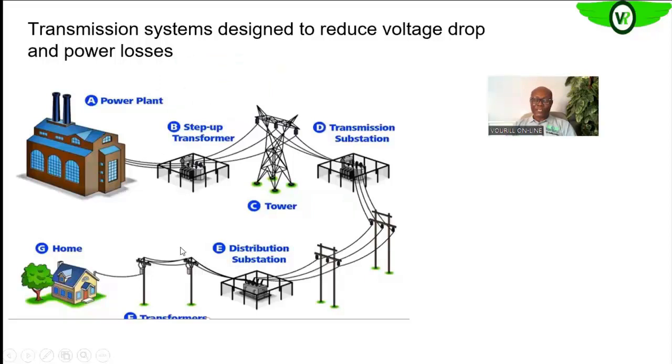So here you see this is a complete power system showing the power plant, then the switch yard containing the transmission transformer or the step-up transformer that will take it, in our case, to 330 kV. This is the transmission line to the sub-transmission system, okay? Then further down, it is stepped down until we get to the distribution levels, and to our ultimate consumer.